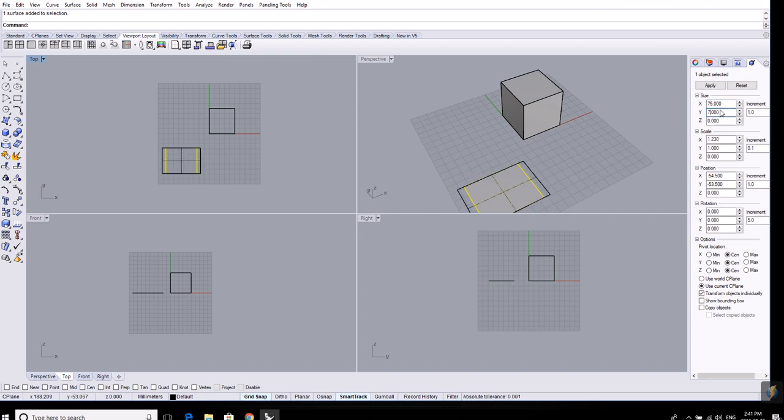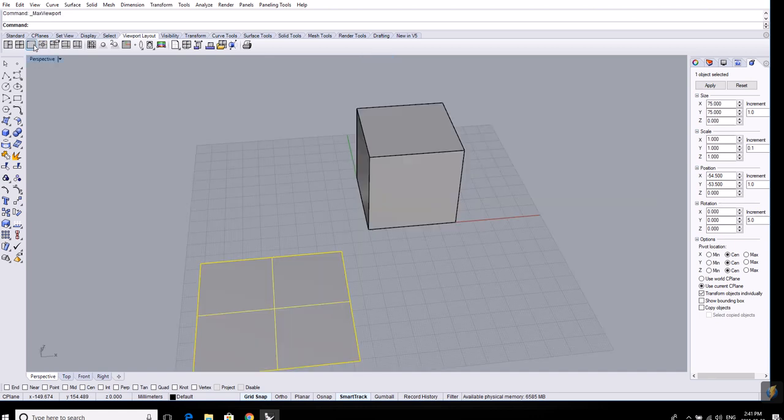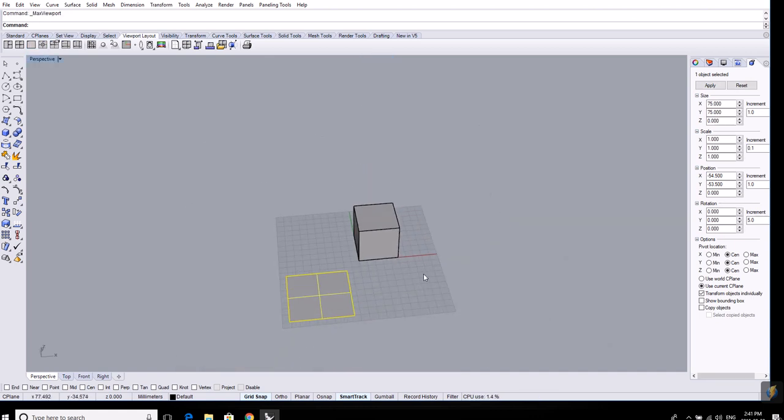This is really simple going on here. This is 50 millimeters of 75. And we're going to use it as an object to cut with. This is something to know when you're working with 3D and you want to create closed geometries. Closed meaning that each of the surfaces is joined. There's no holes here, because when you're 3D printing, a hole in your model won't be able to print. You won't be able to export it in the file type that will go to the printer. So we're going to learn how to make closed objects. Whenever we cut up a solid object, we have to close it up, and I'll show you how to do that in a second.